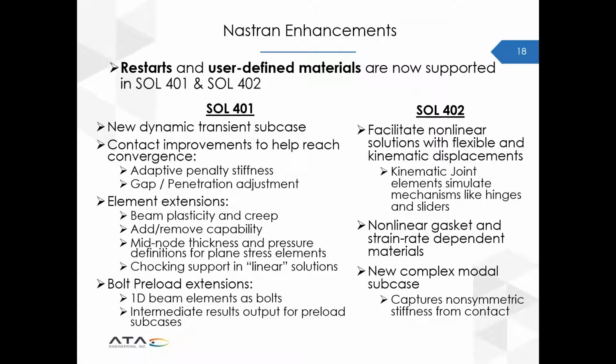There's also some element extensions. I'll point out first that we now see support of beam plasticity and creep. Previously, we only had support for linear materials for beams. And then there's the new element add or remove capability that I mentioned, as well as the mid-side nodes are now included in pressure loads and thickness definitions for plane stress elements.